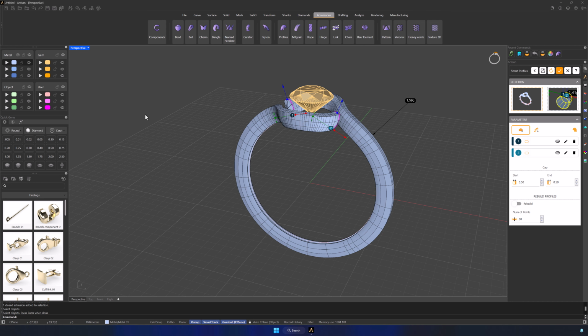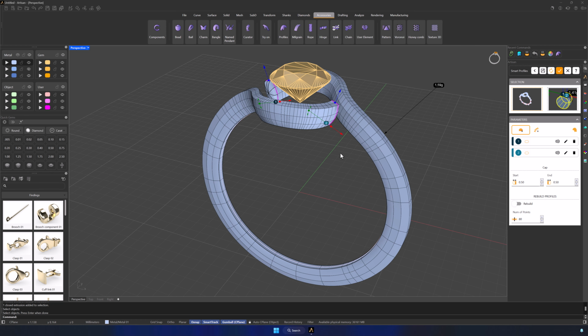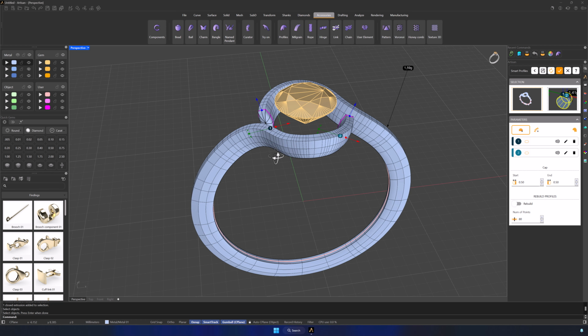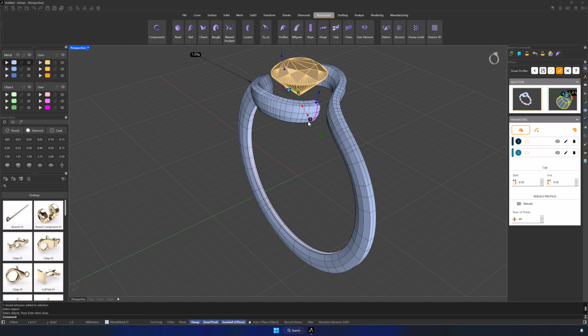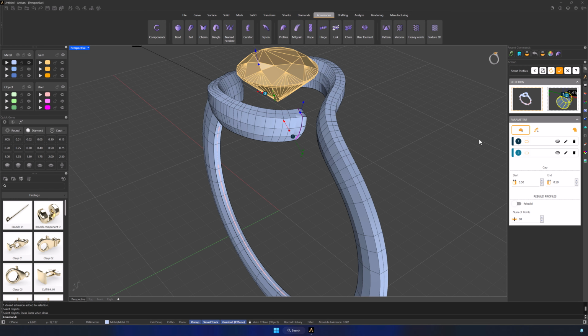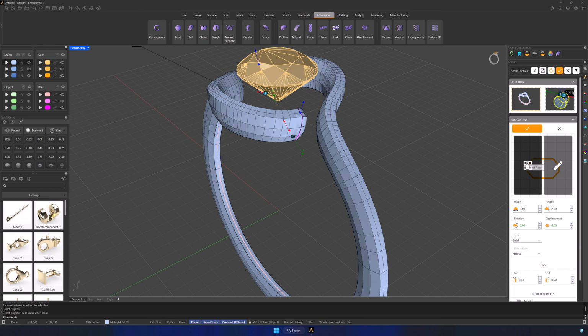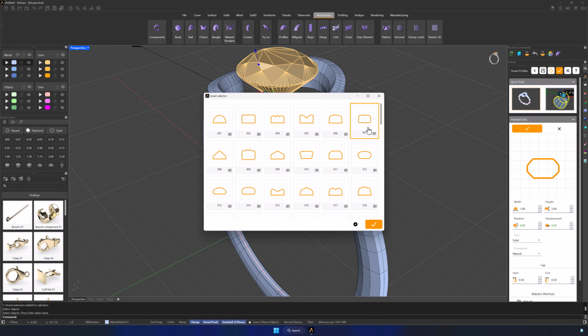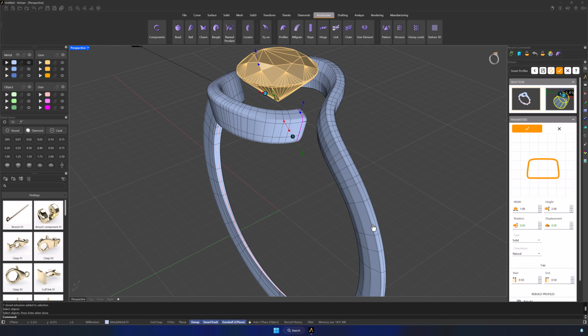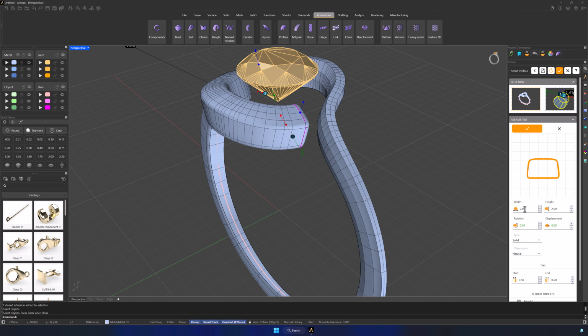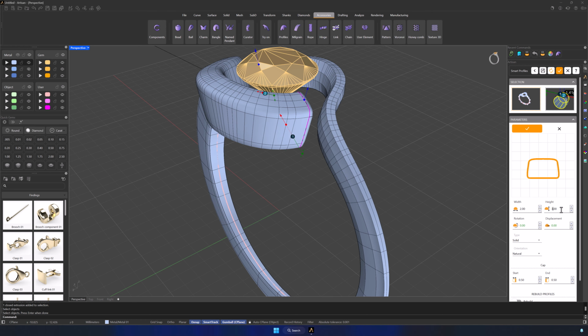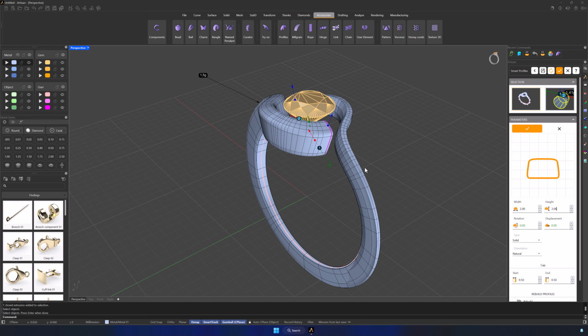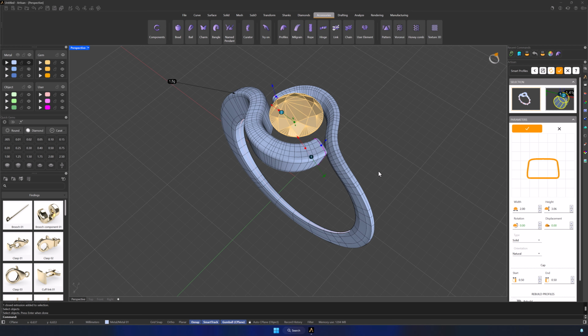We will adjust Profile 1. As you can see, there are small gumballs with numbers that help identify each profile. They also appear listed in the panel. Start by editing Profile 1. Change its curve to number 007 from the Asset selector. Then set its width to 2 millimeters and its height to 3.06 millimeters. Make sure the type is set to solid. Click Accept to confirm this profile.